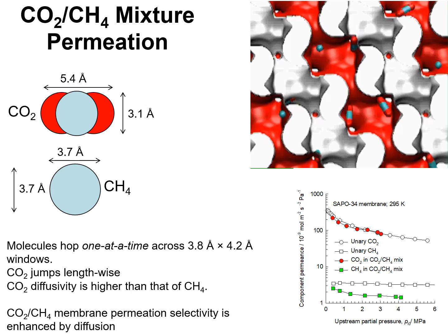Now CO2, because it possesses a quadrupole moment, also has a higher adsorption strength than methane. Both diffusion and adsorption favor the permeation of CO2 across a Chabazite membrane.